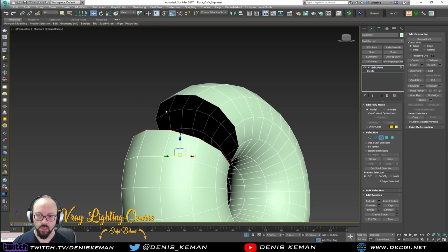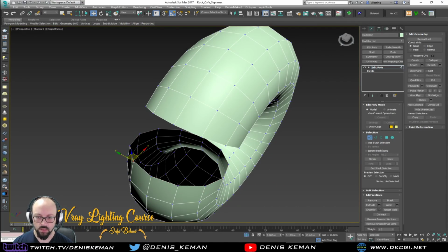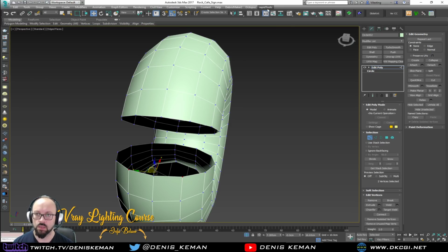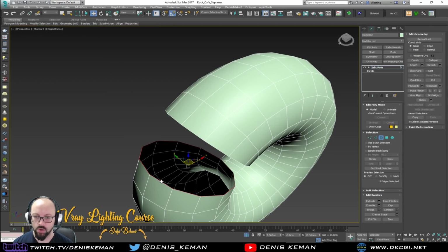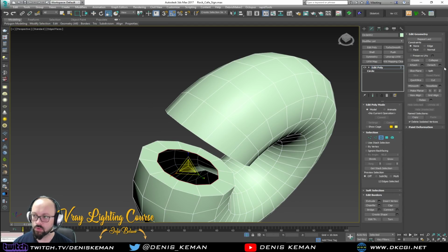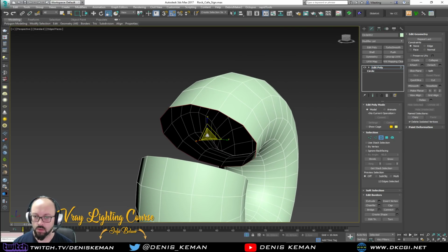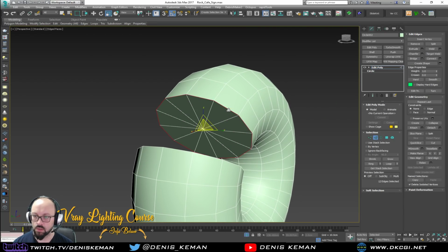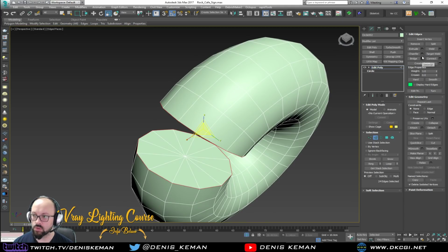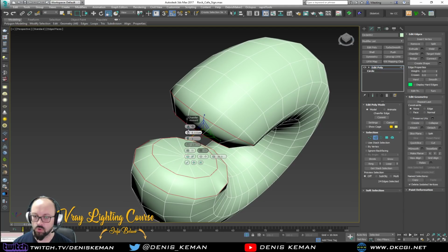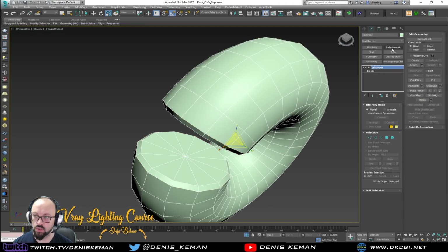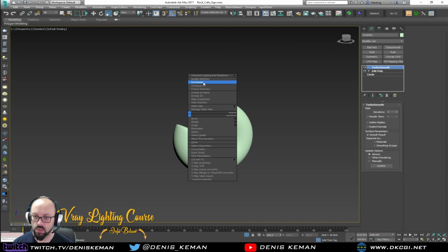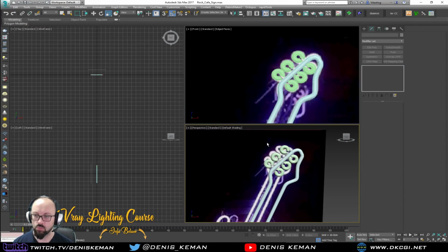Alright, so I'm gonna get these two edges, hit rapid tools, object, topology, rapid QCap. Nope, doesn't work that way. All right. So we're gonna do it this way. Collapse. Collapse. Select both of those. Chamfer. Small amount, very, very small amount. Like this. So when I do the turbo smooth down, there we go. It's gonna hold that thing much better. Much smoother.